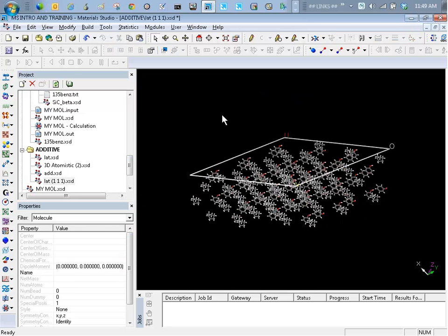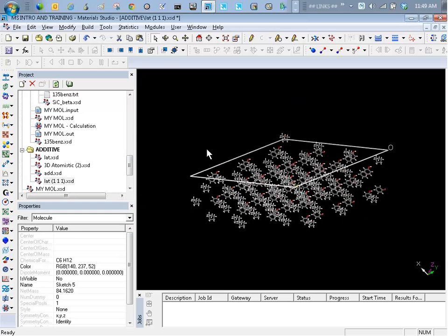Now I've cleaved out a surface, and I can take that surface and start looking at docking new tailor-made additives onto it. And that's actually a very important calculation, because it's quite easy now, once I've built a surface like this, to take a new species, and my new species is the one you can see, very small there, bouncing up and down. Moving it up and down here, I can calculate the energy on the surface, and I can calculate the energy off the surface. I can look at the differential energy between the two systems. That gives me favorable error compensation, whether it's an approximation of my force field, approximation of my geometry, etc. And then I can say this ranking series will actually interact with this surface, and this ranking series would interact in this preferential way. So I can start to look at tailor-made additives onto that.